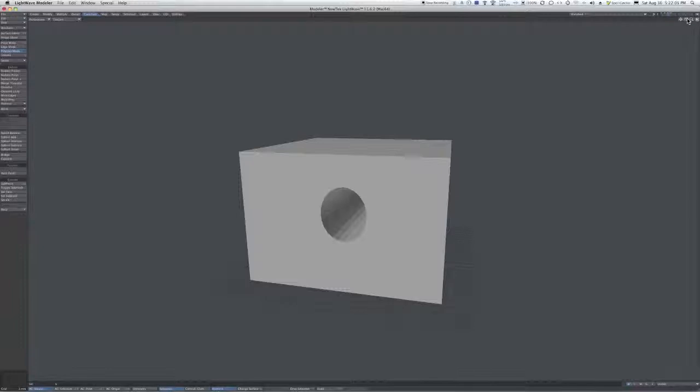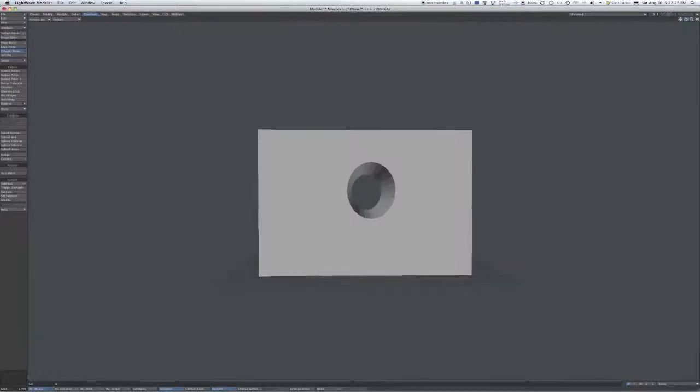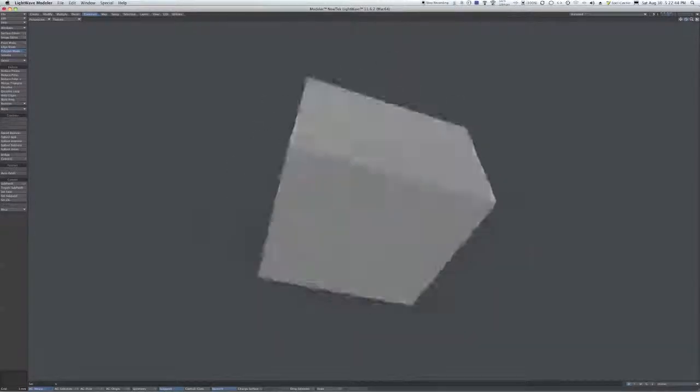Go into Thingiverse, look for hole size guide. I've got one that's very simple to print. It's only like 3 millimeters thick, so it doesn't take a lot of plastic. And I've got from 1 millimeter hole all the way up to like 26, 28 millimeter hole. So if you're going to make something for something around, let's say you're going to make a battery holder, what you would do is you would print that guide out and keep it. And then when you want to make something round that fits, you print the outside first, or you take whatever it is that's going to have to go in the hole, and you put it through the template and see what size hole you need to make.